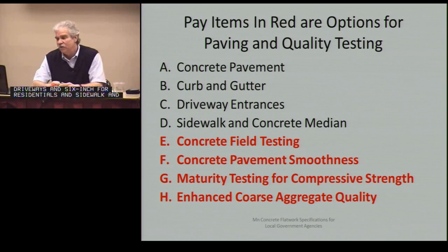But then if they go to concrete field testing, the engineers wanted the ability to take the construction dollar budget and have the contractor hire a testing firm to do the quality assurance side. So when the contractor hires that firm to do that side, then the contractor can't hire the same firm to do his side of the testing. It should be separated out. It seems common sense. We don't have that written in the specs, but that would be the proper way, if you want to throw yourself into a judge or a jury situation someday, you'd want those 2 parties separated.